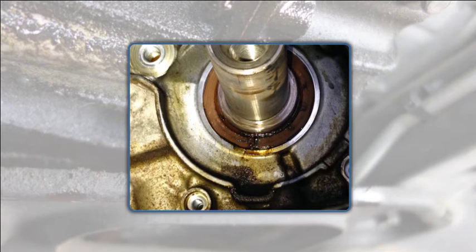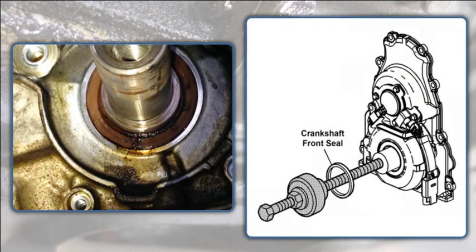Access the seal. Note this may require removing several components, and for the engine rear main crankshaft seal, usually the transmission must be removed. Remove the seal. You can insert a small sheet metal screw into the seal and use a slide hammer. Place some clean engine oil on the new seal and install it using a seal installing tool.